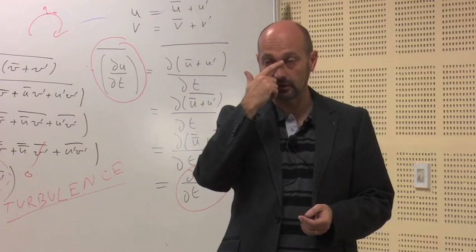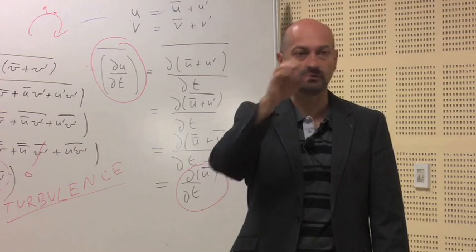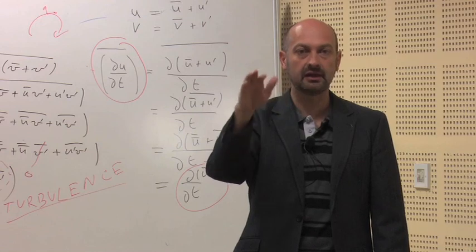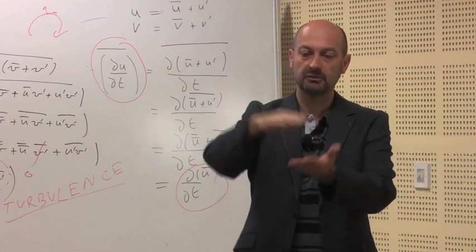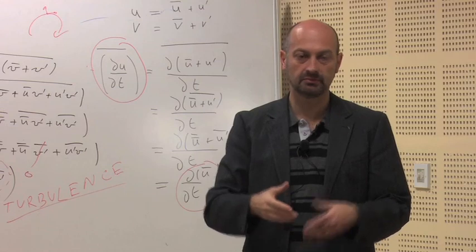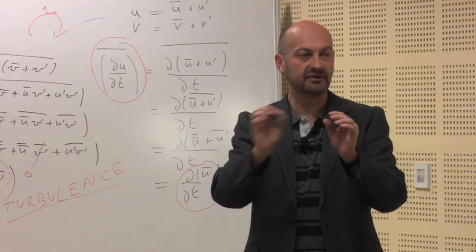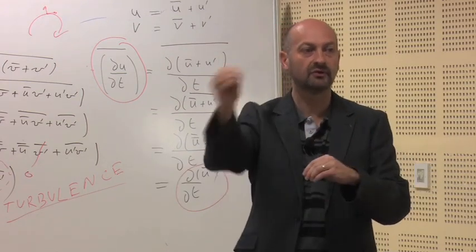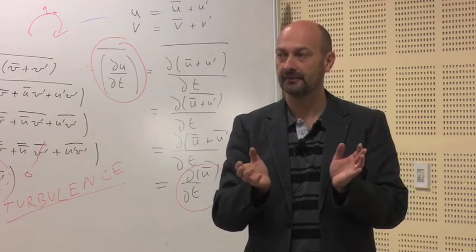And then if you look in CFD software, you have plenty of models. So I can give you some names. You have K epsilon, you have RNG epsilon, you have mixing length, you have K omega, low Reynolds number models. So you have maybe 10, and you can find in research papers, I don't know, hundreds of models. And each of them has advantages and disadvantages. They can be used in that configuration, but not in that configuration, for that Reynolds number, but not for that Reynolds number.